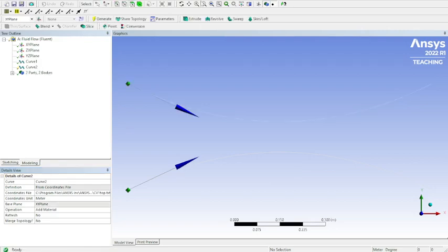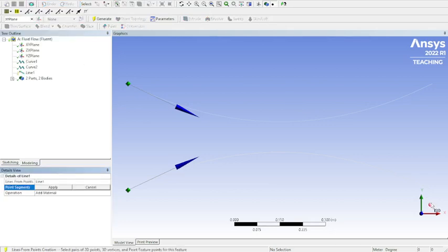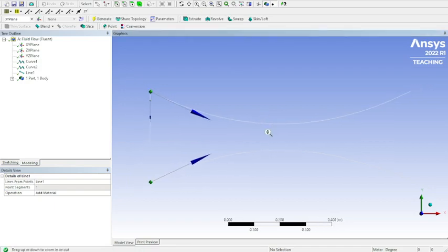Generate. And then Concept, Lines From Points. Where is our point over here? Okay, let's try doing the other side first. You'll have to drag it down. Have some issues with this. Click and drag. Alright, there we go. Generate that. And we'll zoom out a little bit for this other side. It's kind of lighter in that corner, it's tough to see.